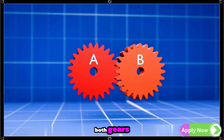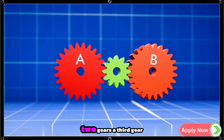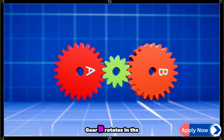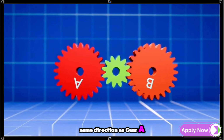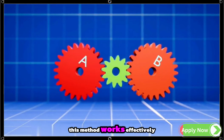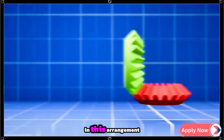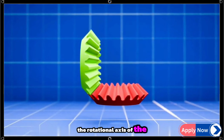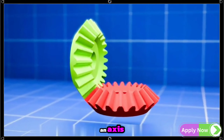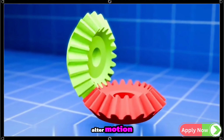But what if we want both gears to rotate in the same direction? We can place between these two gears a third gear called an idler gear. This idler ensures gear B rotates in the same direction as gear A. When the rotational axes of gears are parallel, this method works effectively. Now let's examine a different setup involving bevel gears. In this arrangement, the rotational axes of the gears intersect at right angles. Here, the driven gear rotates along an axis perpendicular to the driving gear's axis. This demonstrates another way gears alter motion direction.